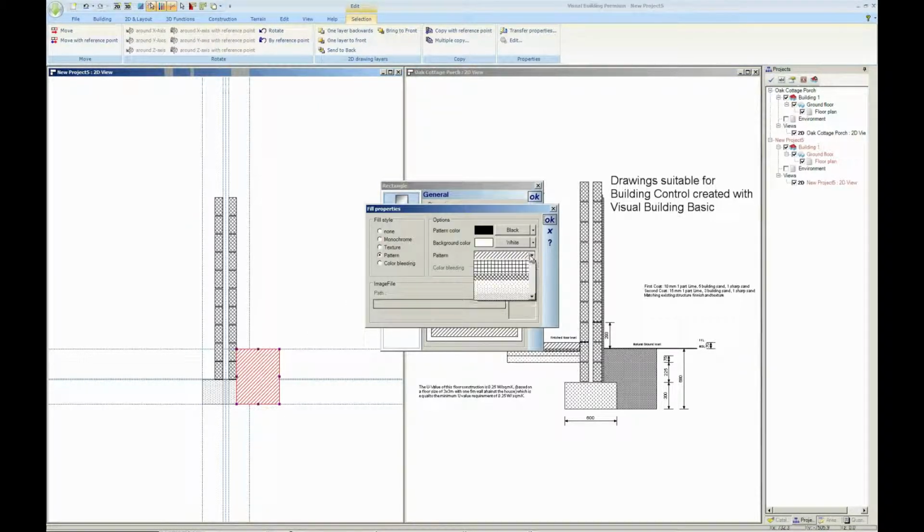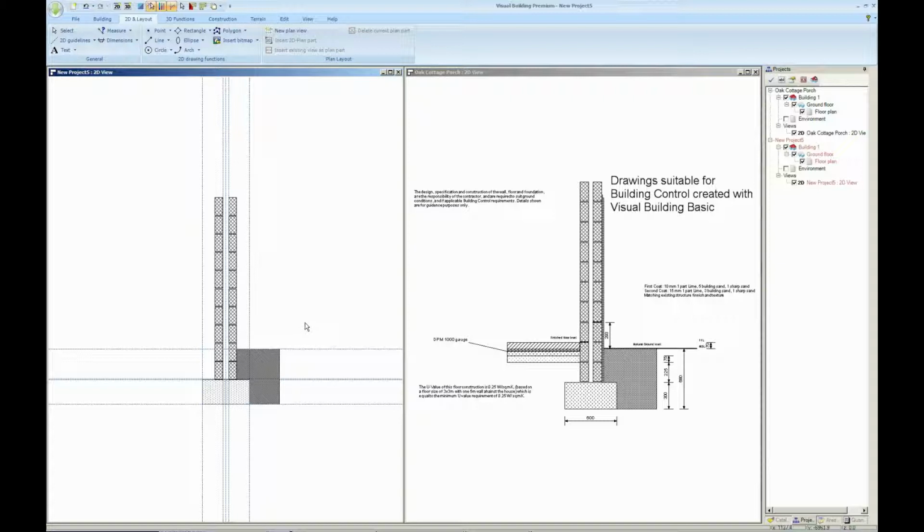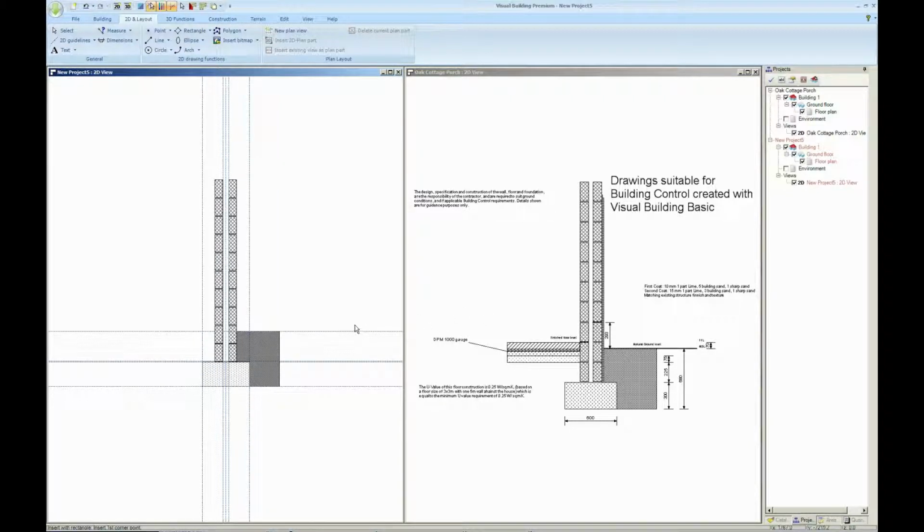Placing the new block. If the block is in front of the existing block, you can set the new block to the background by sending it back one layer. Now to select the hatching for this block. We're now going to create the floor layers using 4 separate blocks.